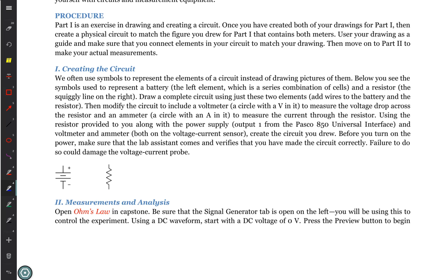So when you connect the voltmeter, how's the voltmeter connected? Okay, the voltmeter is connected in parallel, one before and one after. Which side should I have the positive of my voltmeter on? On the side that I have the positive from the power supply. To do that, I just shove it in, right? They plug in together. You don't have to have anything special.